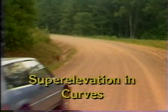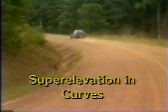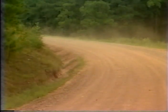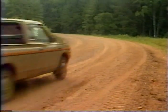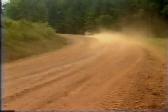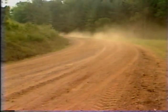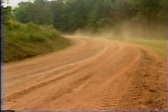The last special condition the motor grader operator will encounter is superelevation in curves. Superelevation is needed for safety purposes. It allows vehicles to go through the curve at a normal speed without being forced off the roadway due to centrifugal force. The tighter the curve, the more superelevation would be needed for vehicles passing through it.